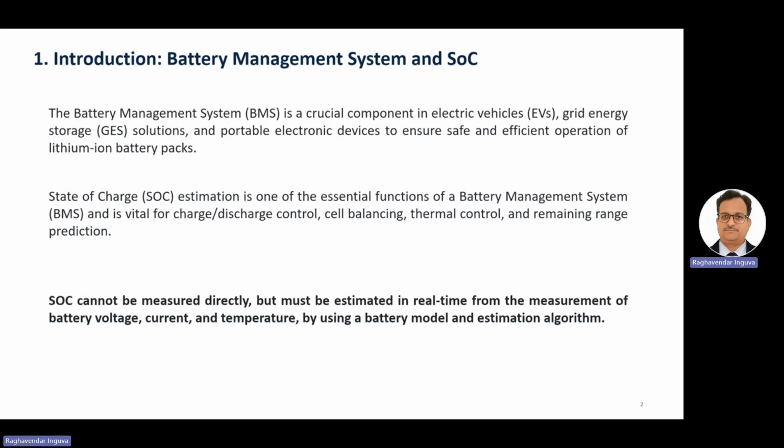Among many parameters, SOC, state of charge, is one essential function of the BMS, where it is very important for charging and discharging control, as well as cell balancing, thermal control, and remaining range prediction.